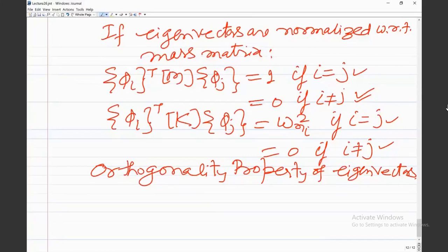One more doubt I had was that we always convert from xy to xi-eta coordinates whenever we have a differently shaped element. Why do we select those kinds of shapes in the first place? Why don't we directly start with rectangular or triangular elements? Because in the physical coordinate space, the geometry may not be regular.